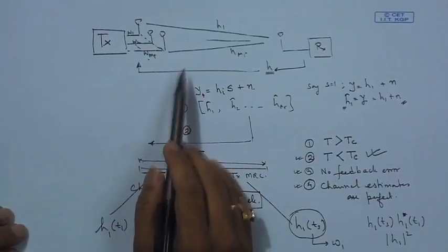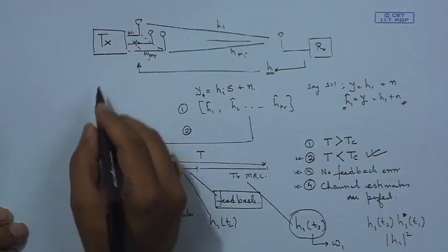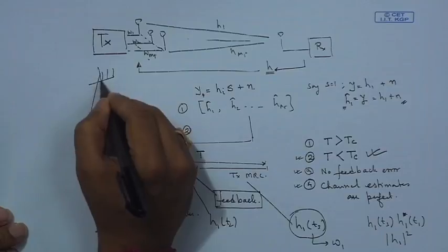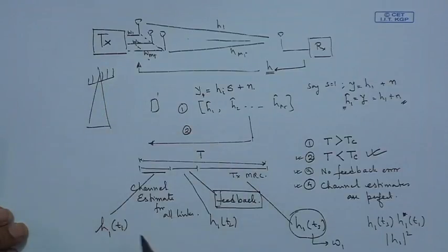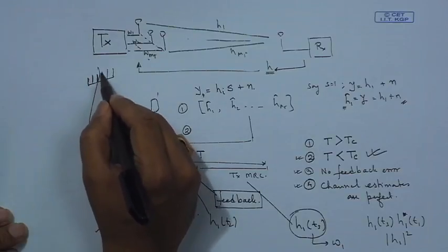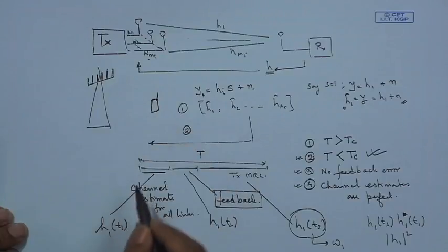I would like to add at this point, when we are considering the transmit MRC case, that means we are considering this expression, this particular scenario, this is very useful. Imagine the situation where there is a base station enabled with multiple antennas, whereas the user device is enabled with a single antenna, and we'd like to do that because we'd like to have more processing capability, more cost at the transmitter. At the user end, we would like to have lower cost.